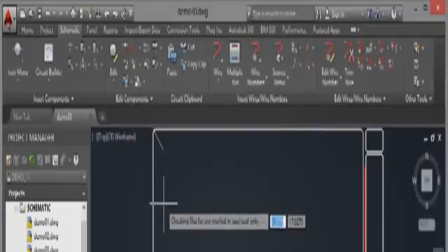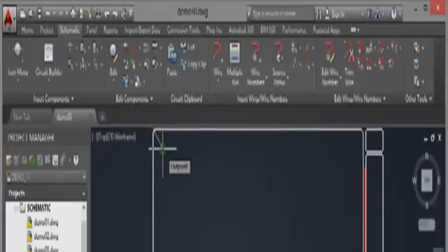Again, we need to pick on our origin. Using our endpoint snap there, we snap to the end of that small line that we placed in the drawing earlier. And we need our zone labels. So again, we'll make sure that these are all in place like so. You'll notice I've just put my caps lock on there. It's always good to make sure that you do these in capitals, otherwise they do look a bit unprofessional, to be honest. Capitals work better on these grids for the X and Y and just the X zone setup as well.